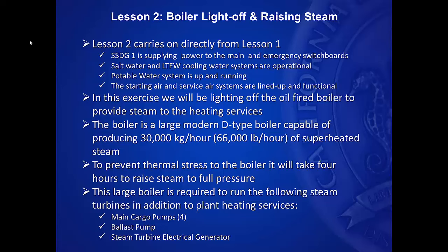If you were to see steam development in the boiler drum, you would need to immediately shut the fires out until an hour has elapsed from the start of the warming up process. The reason this is such a large boiler is that it's required to run the following steam turbines in addition to plant heating services: main cargo pumps, ballast pump, steam turbine electrical generator.